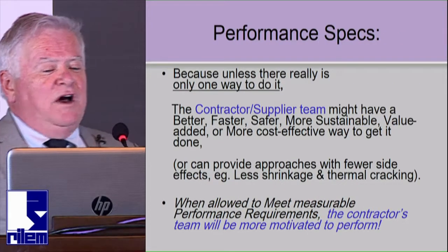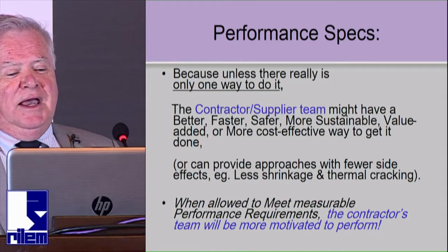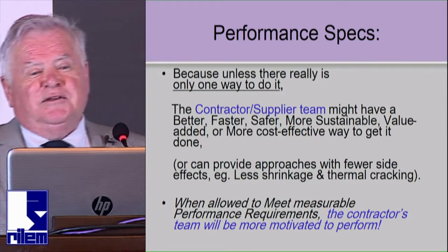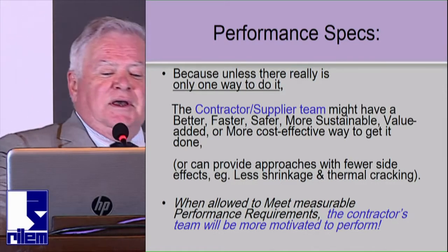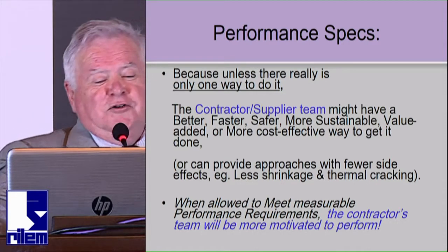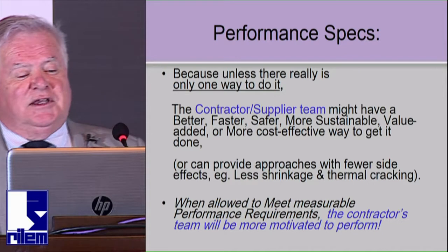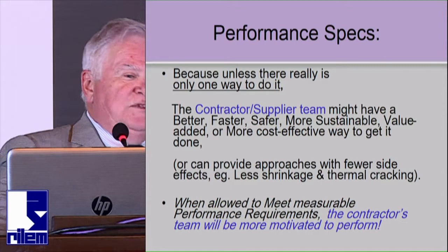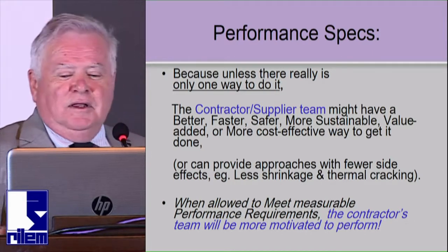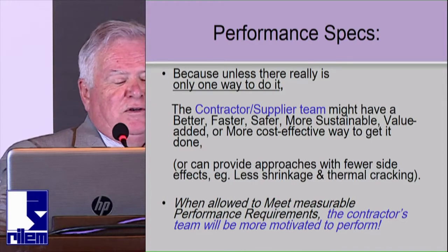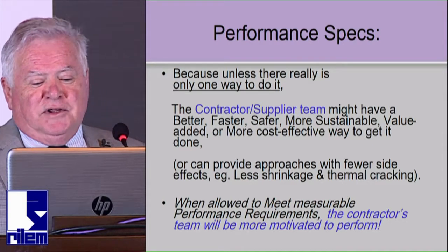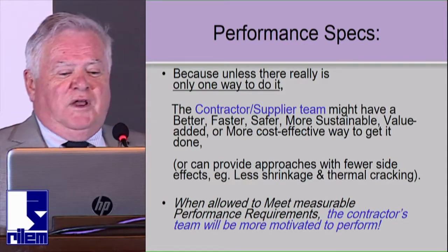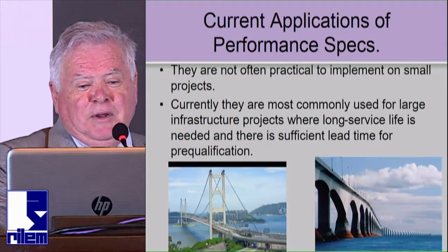And again, there's often more than one way of achieving durability, and there may be a better way out there because there's new materials, environmentally friendly materials, different approaches, different ways of placing concrete, different methods that can be used by the contractor that may result in better performance. So if you set performance limits with proper performance test methods that can be measured, then the contractor can work with the concrete supplier to try and achieve those performance limits, but with a lot of flexibility to do it in the most efficient way.